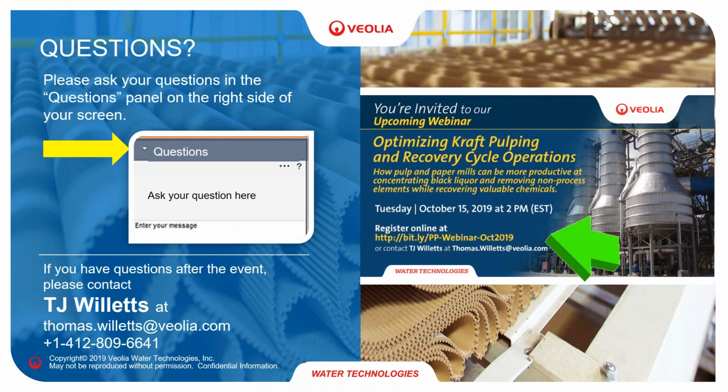So that is a situation that you should prevent at all times, because if that fails, and that was the case study that I presented, then you really have to take down the reactor and replace it or clean it out. So for all the designs that we've done over the last decade, there are two ways of dealing with it. Sometimes the paper mill itself can control calcium discharge to the effluent. So in that case, we just impose a limit on what we can take at the inlet of the anaerobic treatment. If that is not possible, then what we do is we introduce an internal recirculation.